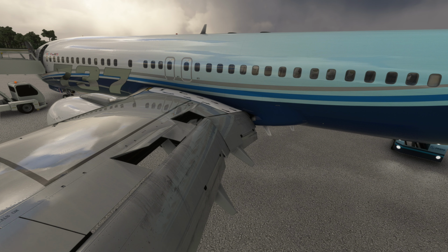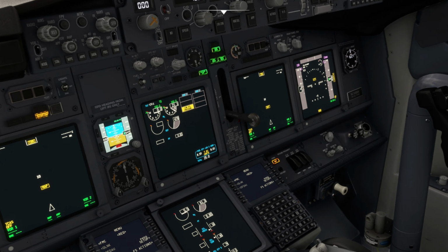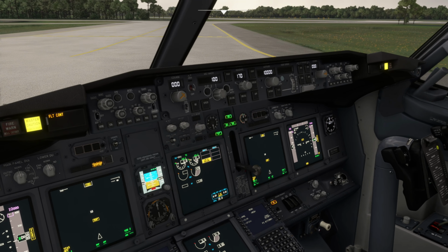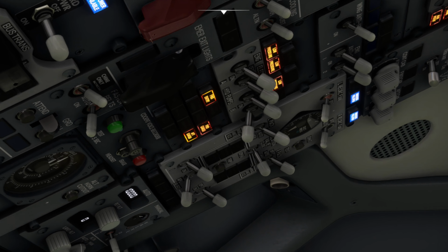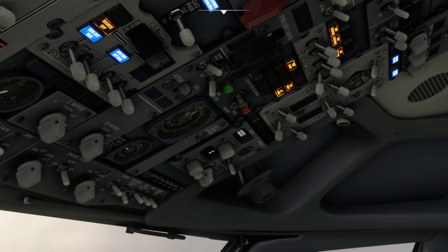There we go. You can hear the drive motors running, the jack screws that are operating the flaps and slats. They have stopped. If we go back into the cockpit, you will see that we have got 40 degrees indicated on flap deployment, leading edge flaps extended. There's just one engine running with no electrical hydraulic systems selected on the bus. The APU is running, but it's not on the bus, either electrically or hydraulically, and we have enough hydraulic pressure to actuate the flaps, slats, and spoilers.